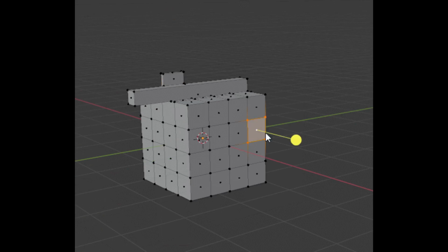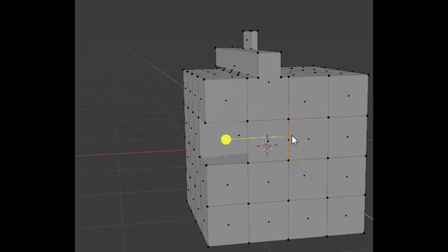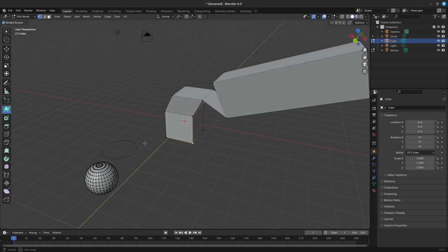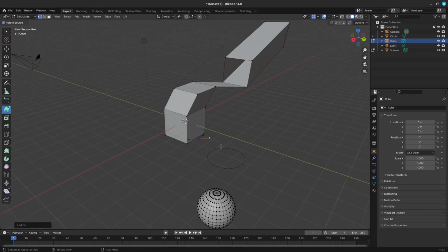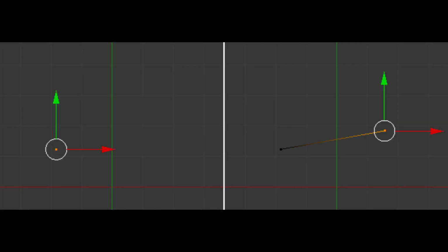The shortcut to do this, if you didn't select the tool, is Control plus the right mouse button. This interactively places new vertices with Control plus the right mouse button at the mouse cursor position. The most basic element, a vertex, can be added with a Control plus the right mouse button click when no other vertices are selected. Because the camera space, the computer screen, is two-dimensional, Blender cannot determine all three vertex coordinates from a single mouse click, so the new vertex is placed at the depth of the 3D cursor.